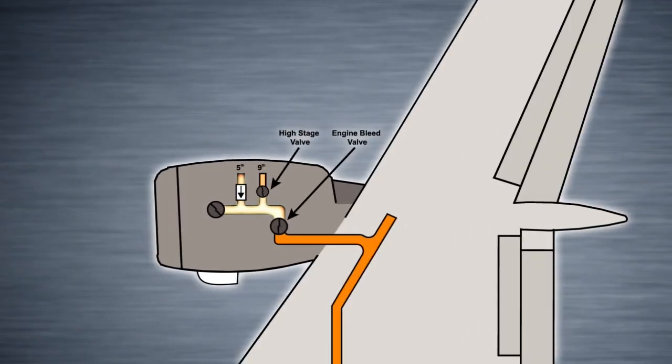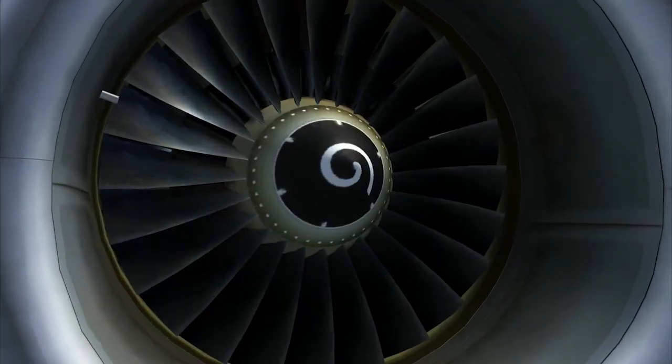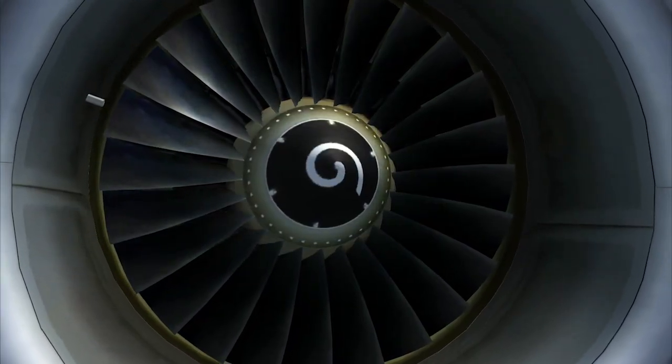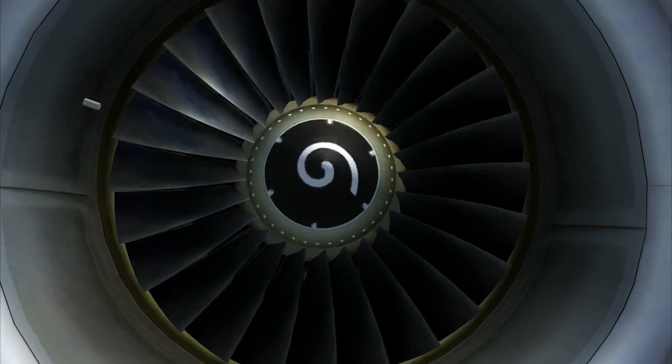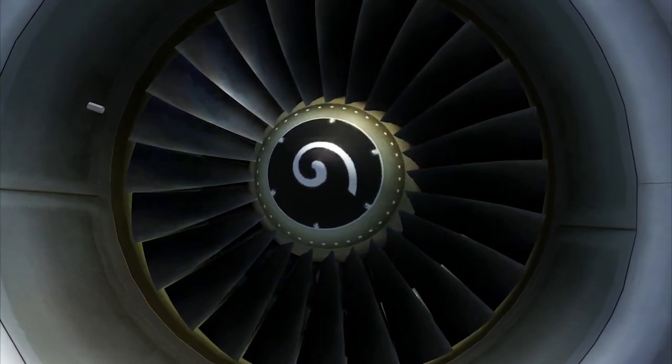The engine anti-ice system uses bleed air to prevent ice from forming on the engine cowl. Ice buildup on the engine cowl could break off and enter the engine with potential to cause damage. To combat this, bleed air is fed around the cowl to prevent ice from forming. There is no active anti-ice system on the fan spinner, but it has a conelliptical shape designed to discourage ice buildup and deflect any ice that does form away from the engine core.